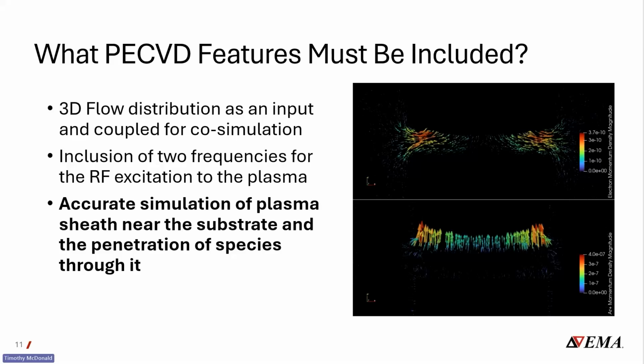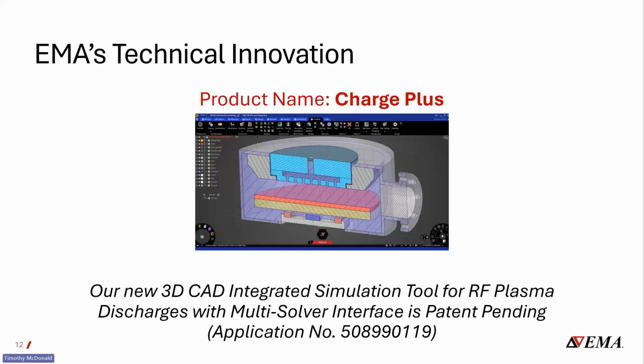Why does it matter in PECVD? The sheath controls how ions hit the wafer. Remember, that's the name of the game. And the ion energy determines how dense and smooth a deposited film is, whether a surface gets cleaned, etched, or damaged. Engineers tune the sheath via the RF power, the RF frequency, etc., to control the film quality.